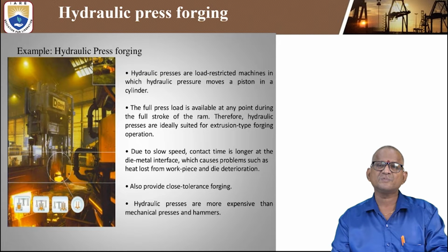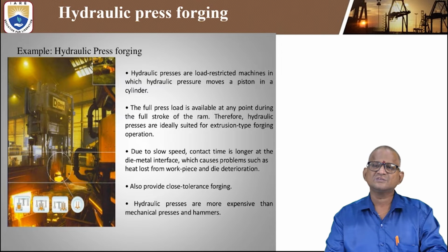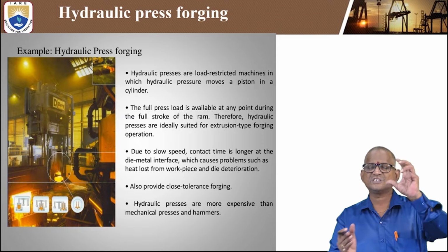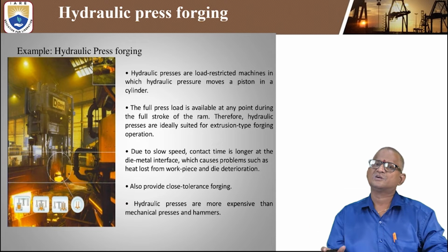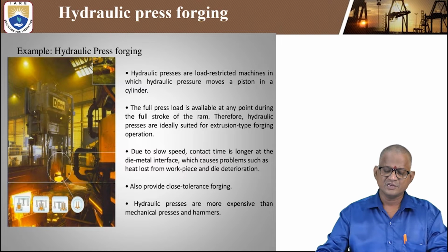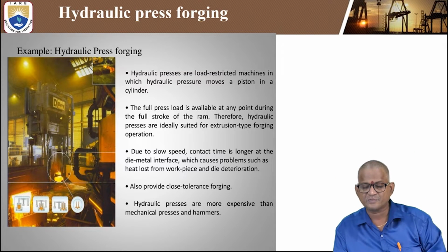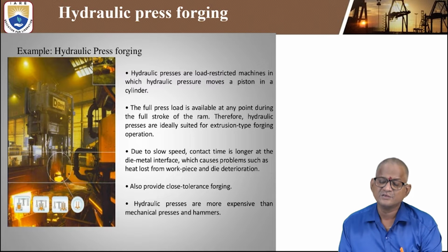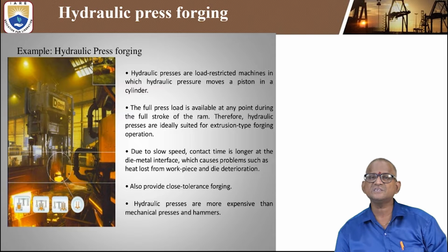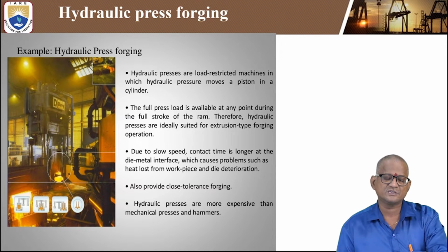What are the applications of these hydraulic presses? Some are used for changing body parts, connecting rods, and crankshafts. In the majority of engine parts, we also prefer the hydraulic press forging process, because we can reduce the shape and size with a nominal force, and the initial cost is only a little bit high.